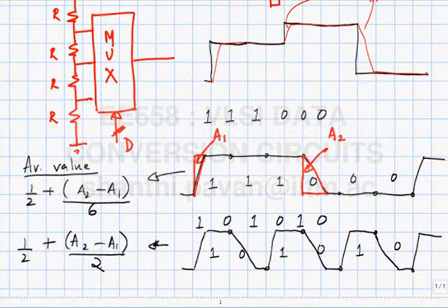If the average value of the input waveform is the same in both cases, the average value of the output waveform should be the same in both cases if the system was linear, right? That's definitely not happening. Another way of doing it is if I subtracted the two waveforms, the average value should be 0, correct? That also doesn't happen. So clearly this is a nonlinear thing.